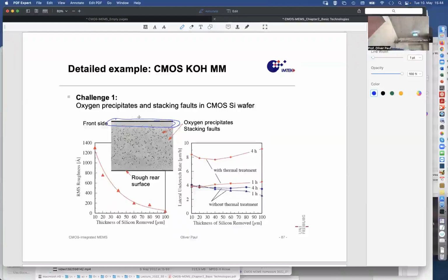But inside it's dirty. And these precipitates, these little particles, influence the etching. Because when you think that a 1-1-1 wall is stable, this rests on the idea that this is a perfect 1-1-1 wall of silicon. But if there are little chunks of silicon oxide hanging out, then of course they can be etched all around and under-etched, and then it goes faster.